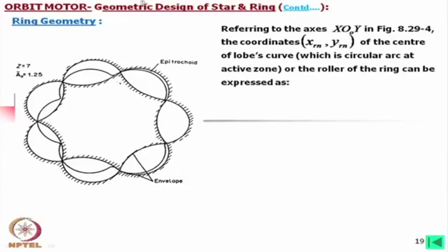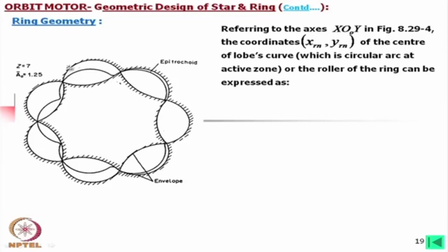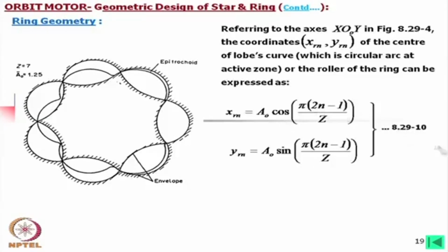Now, to design the envelope, I have already described how this can be designed. Actually, in actual machines we need not bother about these curves, because we are not using these curves; we are using the modified curve, which is nothing but a circular arc whose center is known. This center can be easily calculated using this formula. Then in actual design we use the earlier formula to find this modified star profile, and we use these coordinates to find the points where we can put the circular arc.